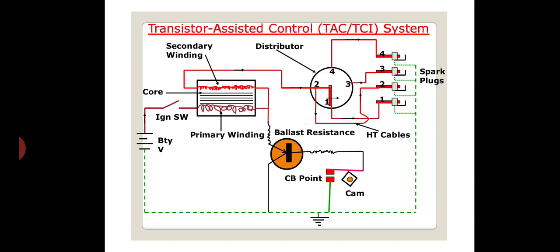In automotive applications, the transistorized coil ignition system, which provides a higher output voltage and uses electronic triggering to maintain the required timing, is fast replacing the conventional ignition system. This system is also called a high energy electronic ignition system.